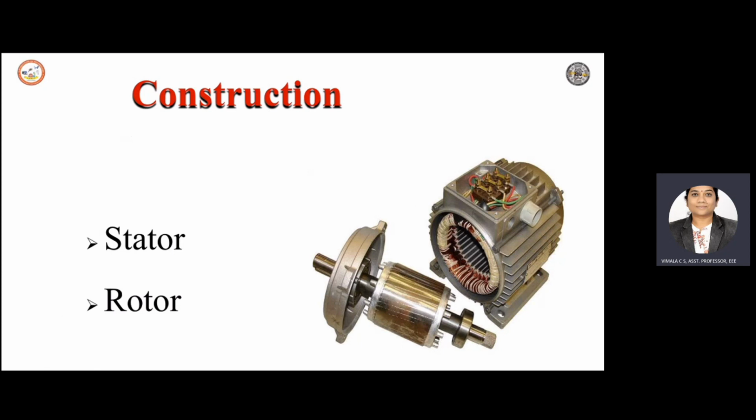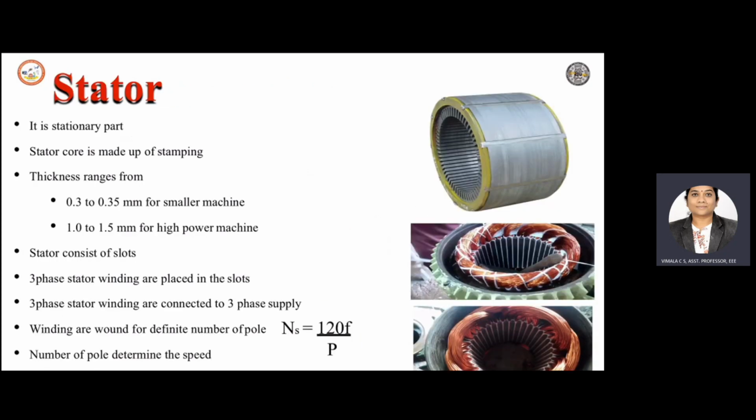When you come to the construction part, we have two parts, that is the stator and rotor. The stator is a stationary part which is mounted on the floor, and the rotor is kept inside, with some gap from the stator. So coming to the stator part, it is the stationary part, as I said.